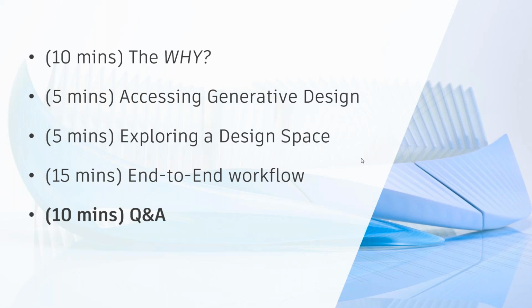Okay, so this last question. If you limit your machining option, like only 2D, does that limit the possible number of solutions and in turn reduce the number of credits? The answer is no. Yes, it reduces the number of solutions, but each study is 25 cloud credits. It doesn't matter how many manufacturing options you are going to explore. But as I was saying, this is the current model.